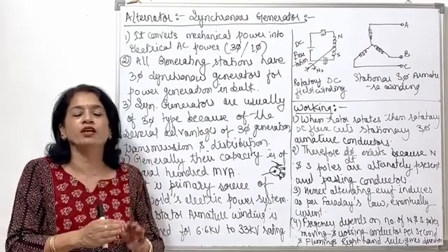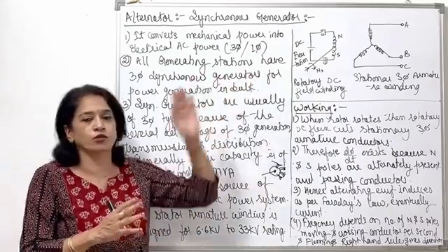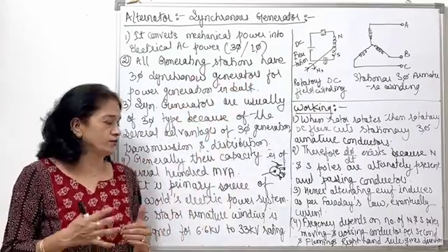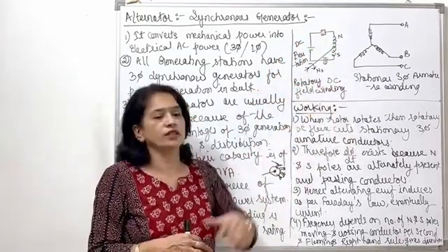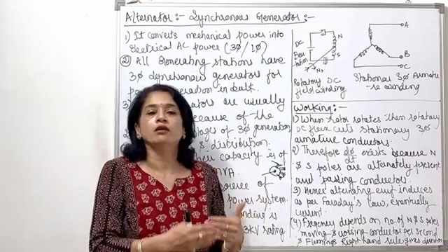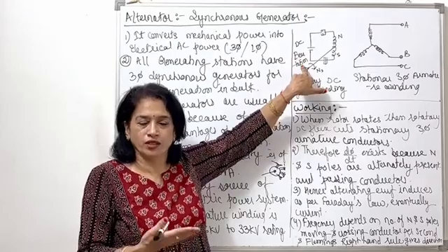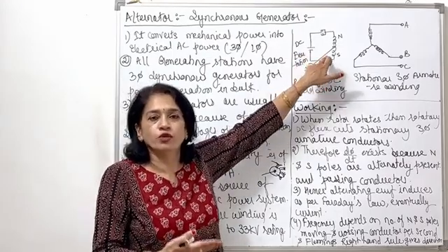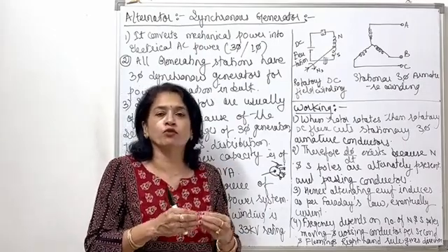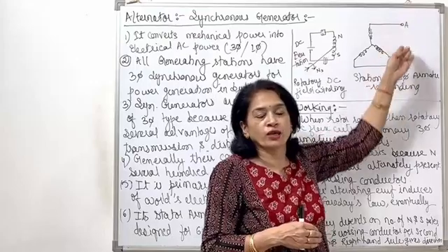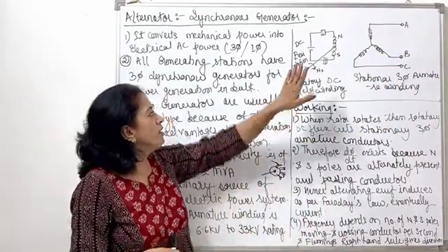But right now I am giving you a very brief, easiest way to understand how three-phase AC power is generated across the synchronous generator or alternator. As I said earlier, we have a rotor over which we apply a rotating DC field winding. Why rotating? Because we are turning it. A DC excitation system gives it a voltage of maybe 125 volts to 600 volts, and because of this small voltage, megavolt ampere power is produced across these ABC three-phase terminals of the armature winding.